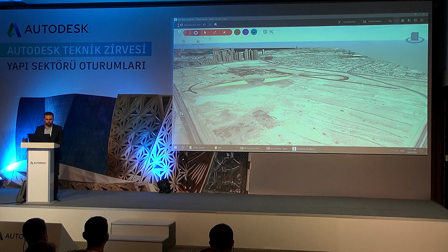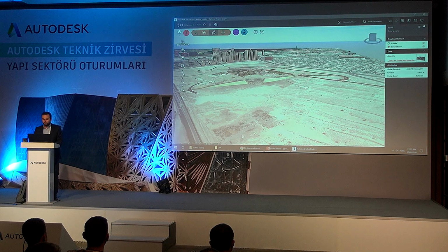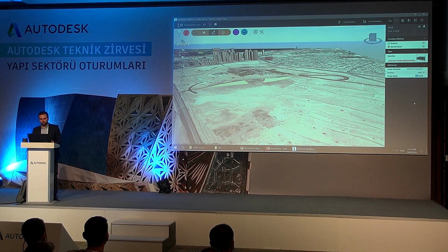We go to the road module, and remember when I talked about the component roads, we pick a component road from here, and this is where we're going to design a road in different ways, either by PI or element-based. It doesn't matter for me. I'm working on the AASHTO metric 2011. If we have the Turkish standard for road design, I can import it in InfraWorks library and use it as well. What type of road? Local, collector, arterial, and that will definitely change the design speed.